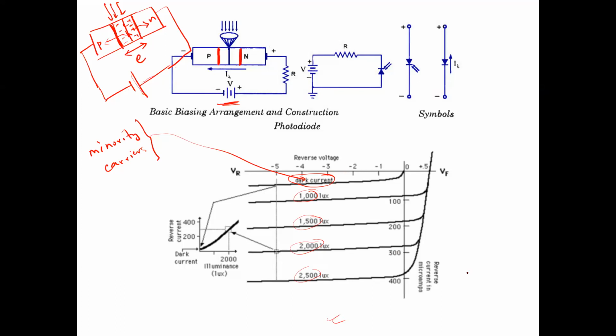And for a specific voltage, like the constant voltage of -5 volts shown over here, if the different values of current at different values of intensity of light are plotted along the x-axis and y-axis, this sort of graph is obtained, which is initially a bit non-linear due to the presence of the dark current, which is working as a sort of noise over here.